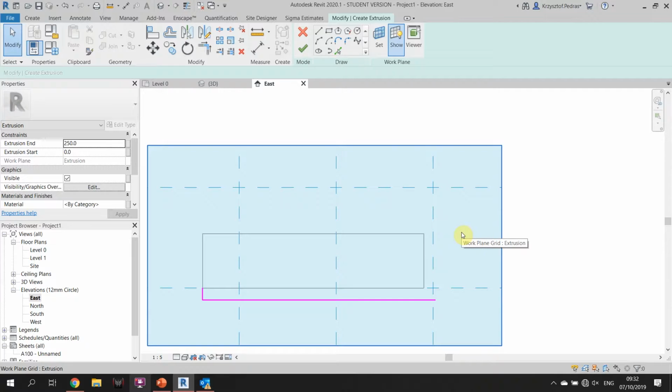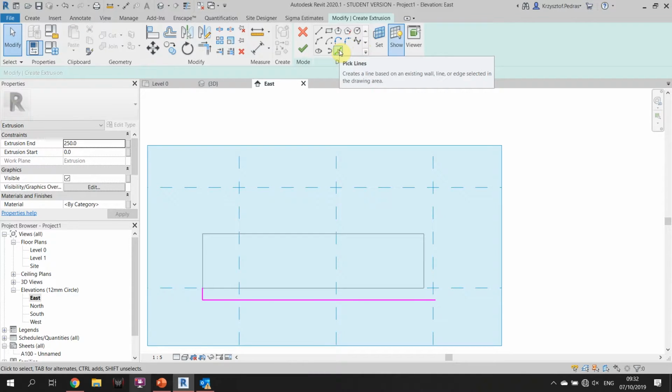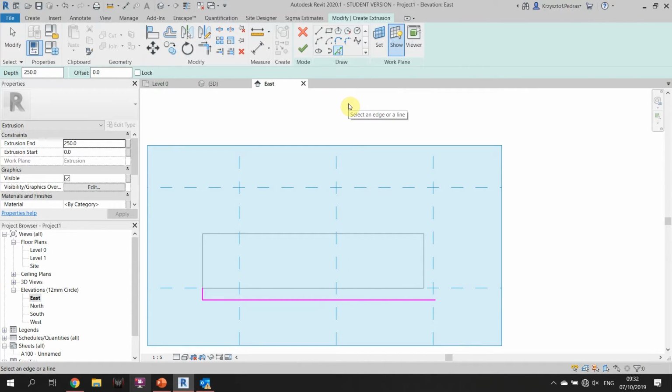And a second way to create a sketch using a line is you have plenty of options here. For these options, for example, pick lines. Let's click on this one, this little green line in the option tab. And what it does, that you can basically use existing lines to create a new line, meaning that we can use this object to create a sketch for our mortar.